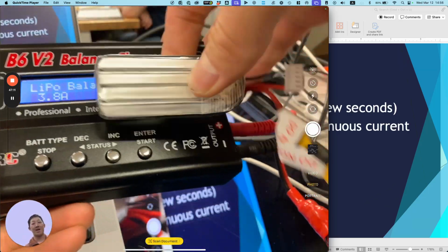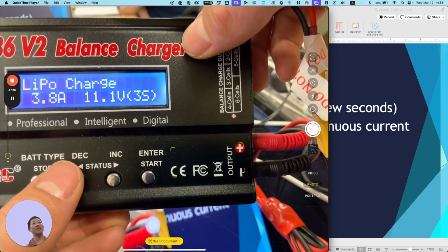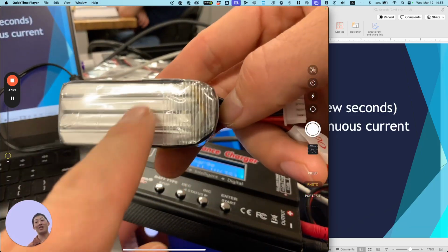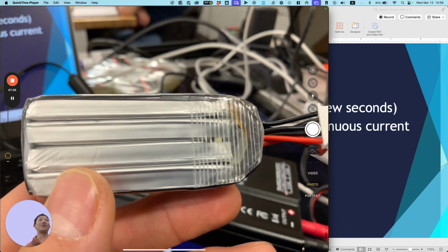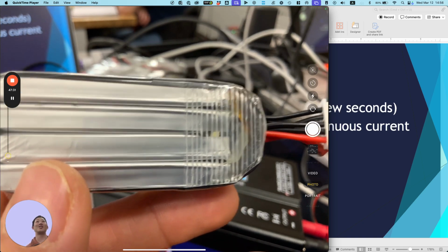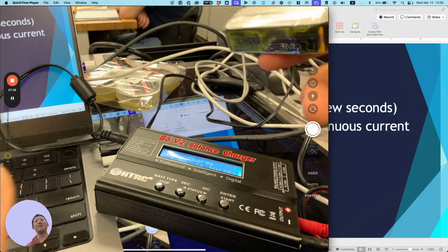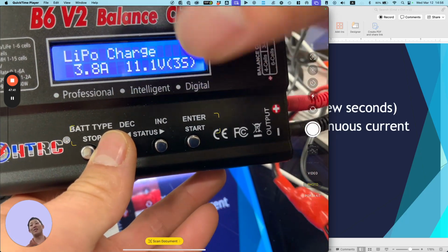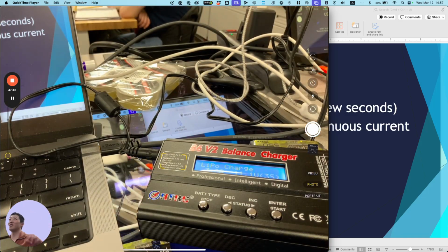All right. The other type of charging, which is just called normal charge, just looks at the total voltage. It doesn't care about the individual cells. It just sees, what's 4.2 times 4? 16.8. You got to 16.8 volts total charge. So that one is going to be a little faster, but again, for the longevity and the health of the battery, you better do it on balance charge. They both charge. It's just that one accounts for the different cells, the other doesn't.